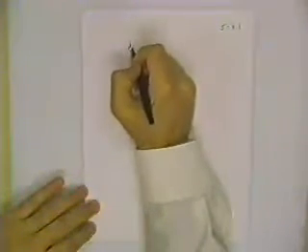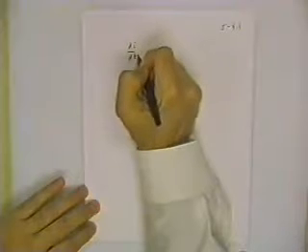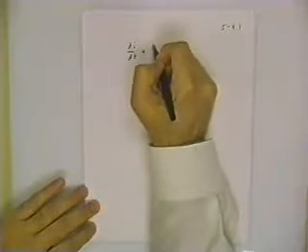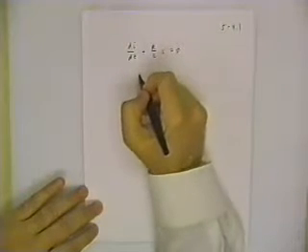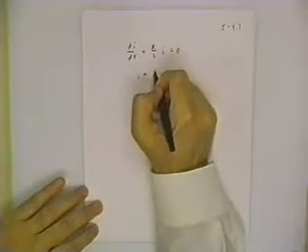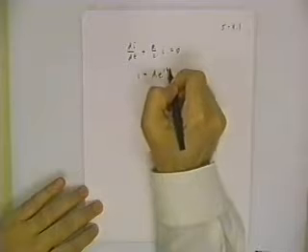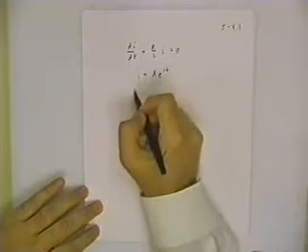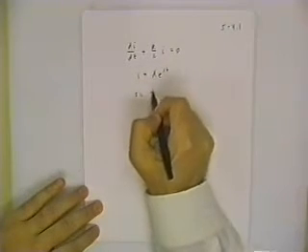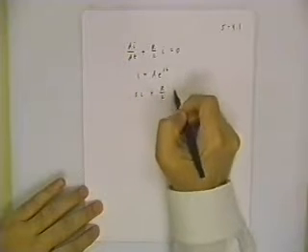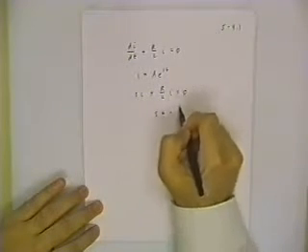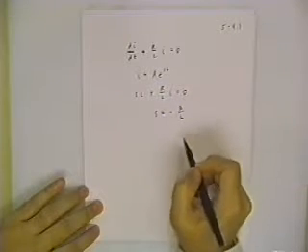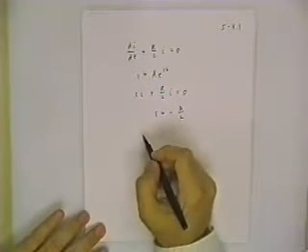And so we have, if di/dt plus R over L I is equal to 0, this tells us that I equal to A e to the st is going to be satisfied by sI plus R over L I equals 0. The s turns out to be negative R over L.